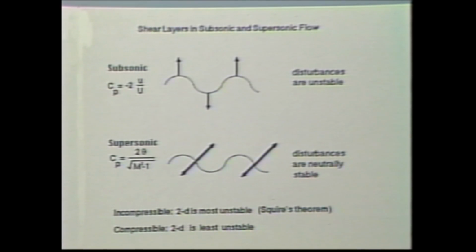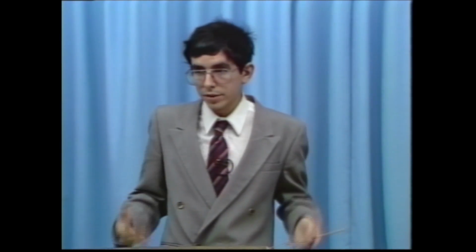And again, I want to emphasize, this comes out of the fundamental fluid mechanics. This is a fundamental law of physics that we've got to fight in order to get the fuel to mix. Right? Now imagine if one of these streams, let's say this side is the hydrogen fuel, and this side is the air. Imagine what happens as these two are moving along. Well, disturbances don't induce mixing readily. So those two streams continue on their own merry way without mixing effectively, unless we do something to enhance the mixing.